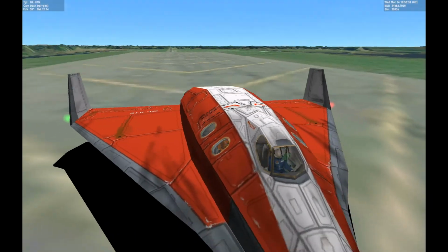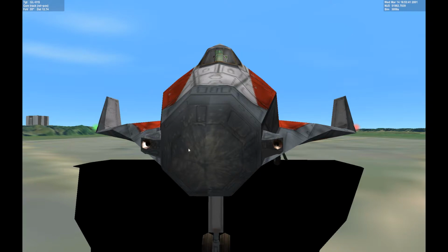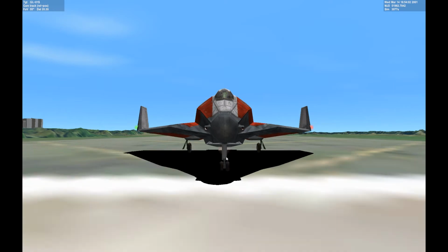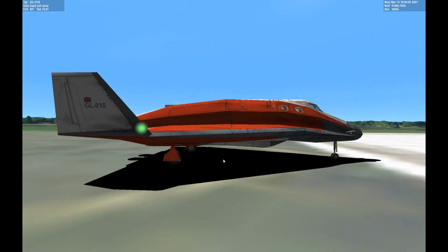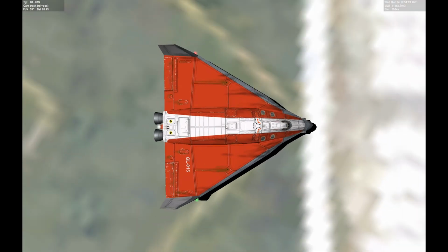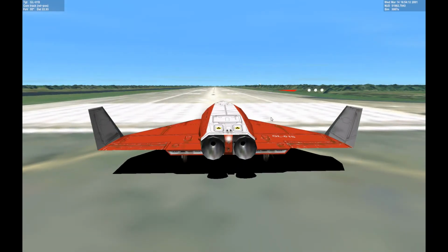Translation. So now what happens if I fire this one and this one at the exact same time? Well, both are firing outward from the center of gravity. Both are offset from the center of gravity by the same amount. So if you draw a longitudinal line right here, the amount cancels, and it's the effect of having a single rocket at front or behind you, which means translation means you scoot forward or backwards, or you scoot side to side, or you scoot up to down based on whatever is being done.